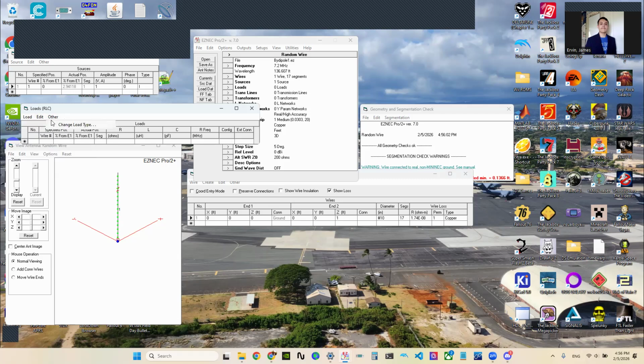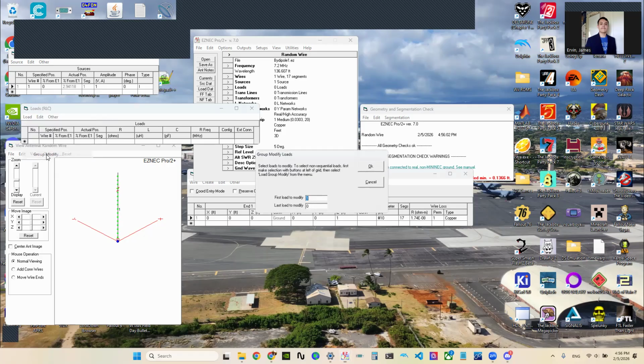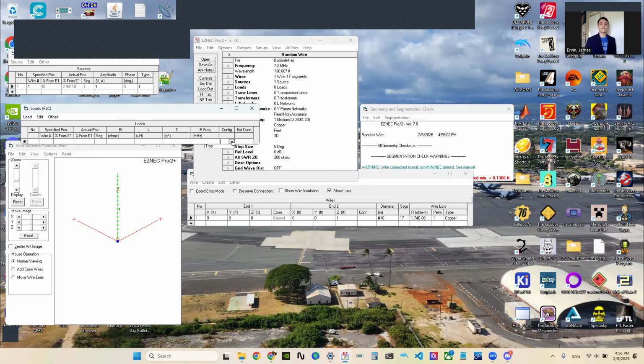You can go and hit load type. Let me see. Load. Oh, geez, I don't know which one. Yeah, here it is. So you can do series, parallel, and trap. So you have all your various settings here. If you have a 100 picofarad capacitor in parallel with a 10 microhenry inductor, and you calculate it has a series resistance of 1 ohm, you can model all that in here and it'll give you an estimation of what it's like. Any other questions?